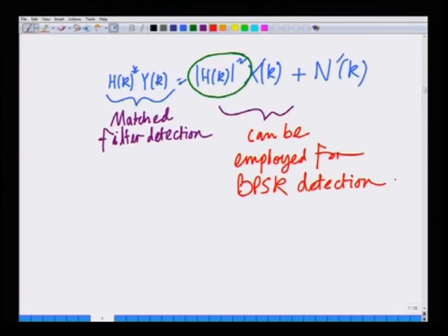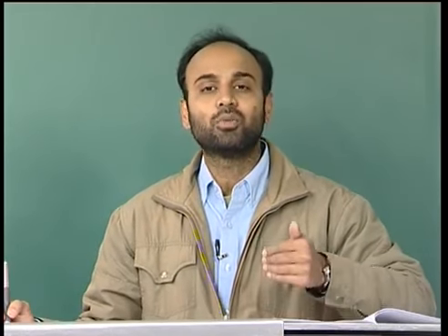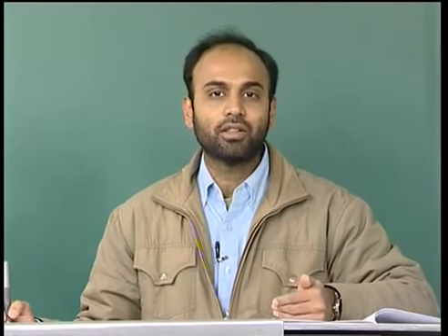So this can be employed for BPSK detection, and of course one can also be slightly more fancy and slightly more technically involved. As we said, zero forcing results in noise enhancement. Matched filtering is not optimal in the case of high SNR scenarios. So what is the optimal thing? The optimal thing we already saw in the case of MIMO communication systems is the MMSE receiver, and one can naturally employ the MMSE receiver.